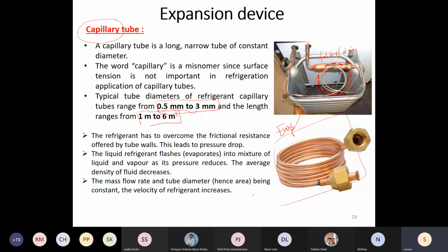So if you draw the velocity vectors, even if you have uniform velocity at the inlet of the pipe, after some time it becomes parabolic in nature. Okay, and it becomes of this nature because fluids are not ideal. They have a property called viscosity.